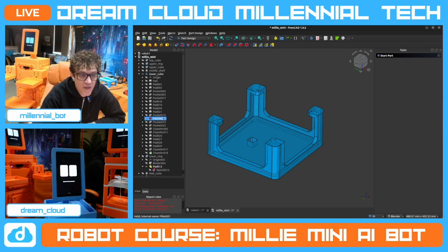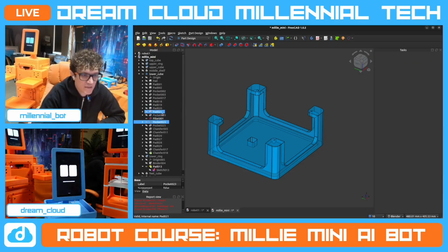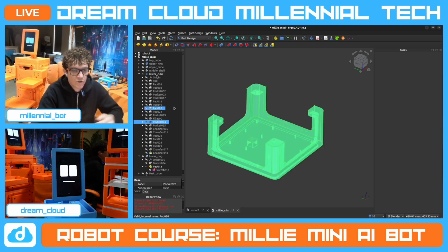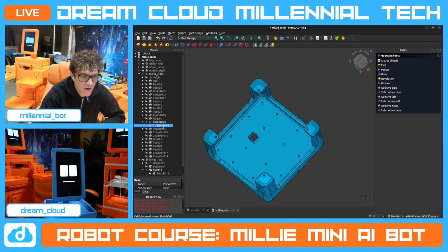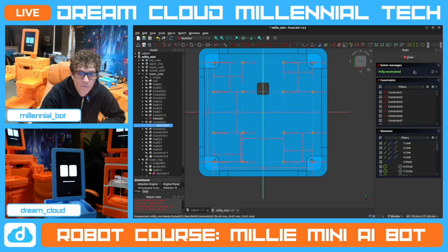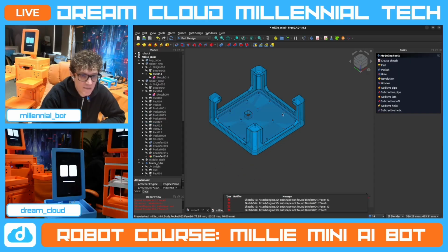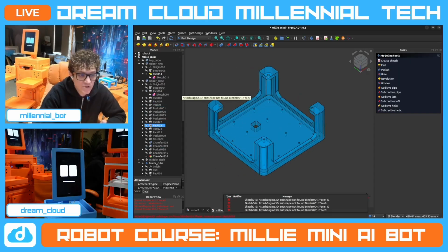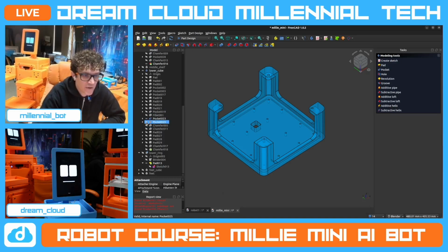And to do that, all you have to do is use this tool up here, which we'll go over. Again, I'm going to build this completely from scratch, so I'm just trying to go over how these things flow so that you're not guessing in the future. And then we did a pocket of all of these holes, which is interesting, right? So we created this grid and then we put all these different holes on it and then we just do a pocket. So just think about holes or pockets and cuts or pockets, and taking material out, subtracting from the model is just a pocket, and then adding to the model is just a pad. So that's the language of FreeCAD and I think most other CAD software.